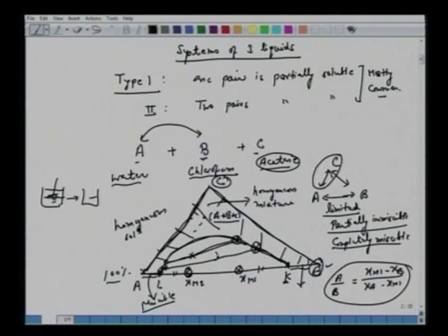All right. So let's again try to understand this extraction. If we recall, before this extraction, we had a discussion on distillation. So we had liquid and vapor, and of course we had only binary components. So when we had this phase diagram, liquid and vapor, and there if you choose a fixed temperature and draw this horizontal line and you have a mixture of liquid and vapor, allow them to come to equilibrium, then there is separation. Vapor is rich in one component, liquid is rich in another component. But you have both A and B in the liquid as well as in the vapor phase. So that's a phase diagram.